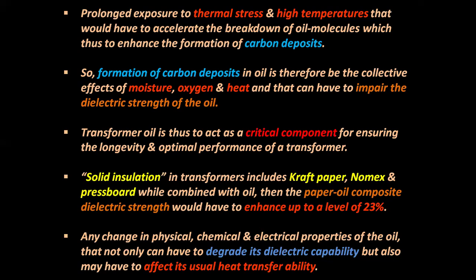So, formation of carbon deposits in oil is the collective effect of moisture, oxygen, and heat, and that can impair the dielectric strength of the oil.